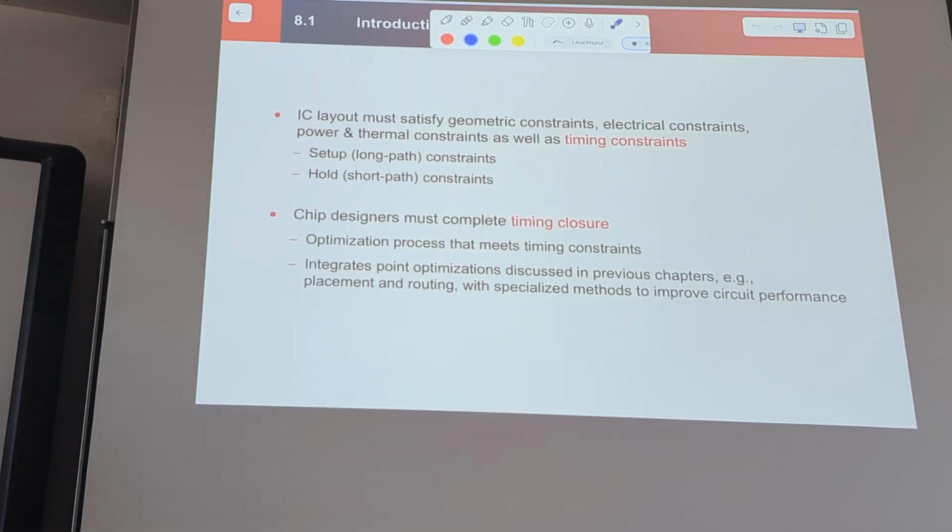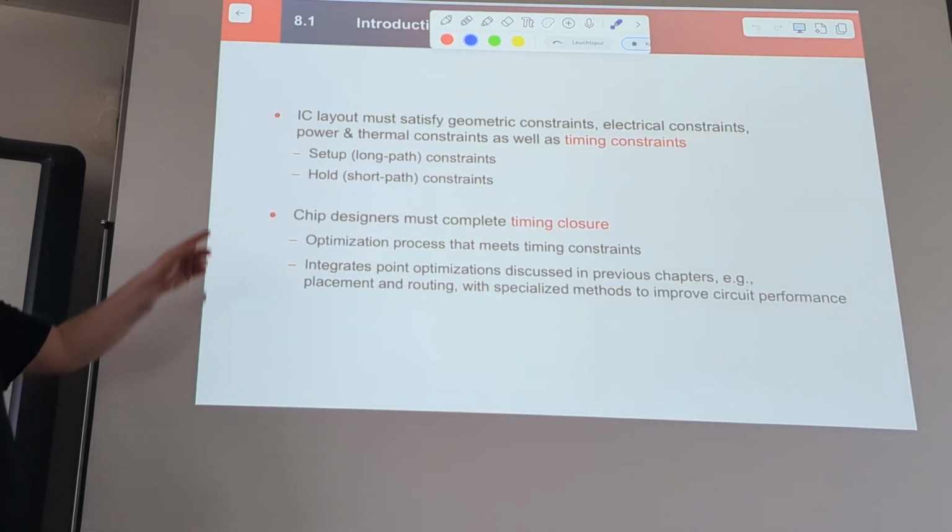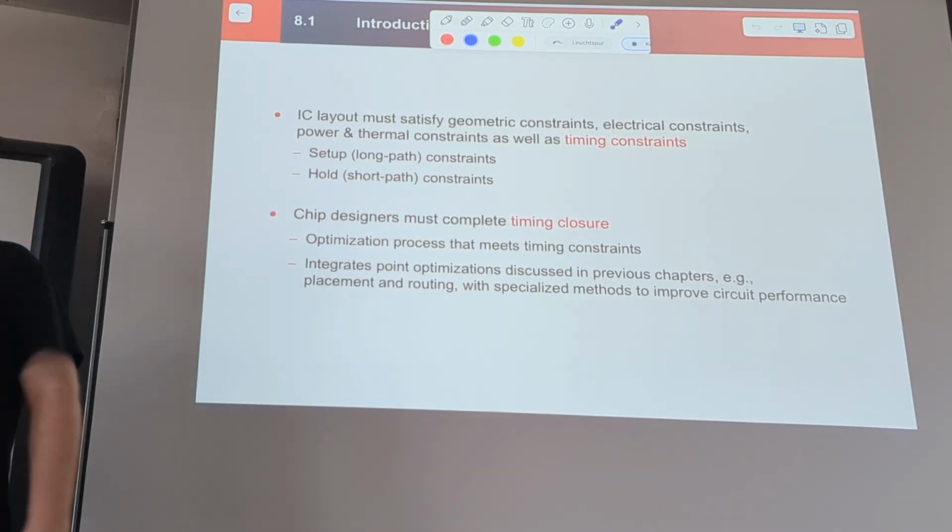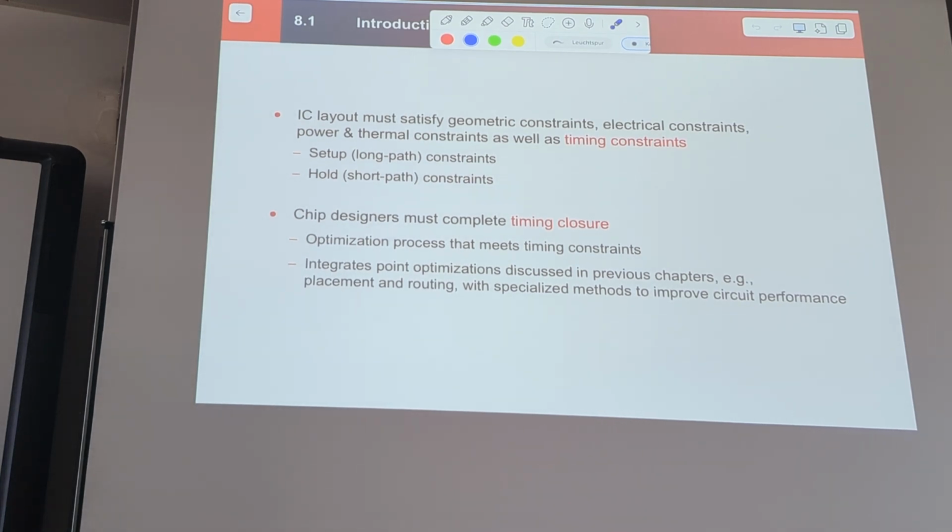So mentioned here are timing constraints, that's what I introduced. I looked only at the setup constraint, which is limiting your maximum clock frequency. But you have one other constraint, and that is the hold timing. So you must have something that will avoid your signal changing too fast at the output of the flip-flop, because then you have a hold violation.